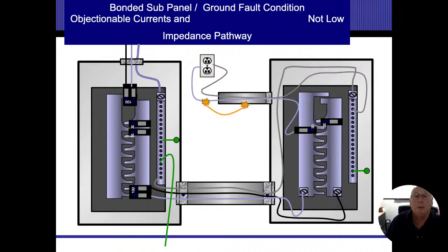Now, either way, with or without the bond, if I had that ground fault and everything else was connected, I would still be good. So here we're showing a phase, the case fault, energizing my case, energizing my panel, energizing my conduit, energizing the other case, energizing my bond, and that gets my power to the neutral, free flow electricity. My breaker is going to trip. This is all good, so it's not going to harm us there. But the biggest problem is we're inviting electricity under normal usage, not under a fault usage.